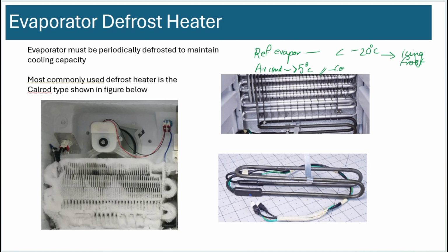You will have condensation and water in air conditioning evaporator. So when you drive cars and you turn on AC, when you park the car, you'll see a lot of water coming out the bottom of the car because of condensation. But you'll never see frost like this. And because of this, most of the refrigeration air conditioners have a defrost heater to remove this ice. Okay.